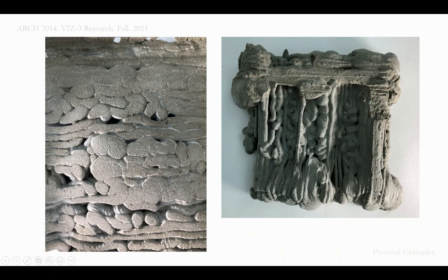And all of this, I controlled it enough to realize that this was going to happen at the corners or at the edge, because I knew exactly what I did with my G-code. I couldn't tell you exactly what final form it would take, but I knew these blobs would happen at these corners, because I'd programmed it to extrude a lot of material at these points. Because all of this is just a big game of connect the dots.